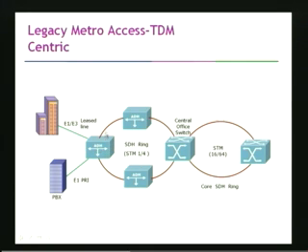These are add drop multiplexers, which are connected together to form a ring, and several of these add drop multiplexers are then aggregated at a central office switch, which may be connected in another core ring, an SDH ring, either STM16 or STM64.